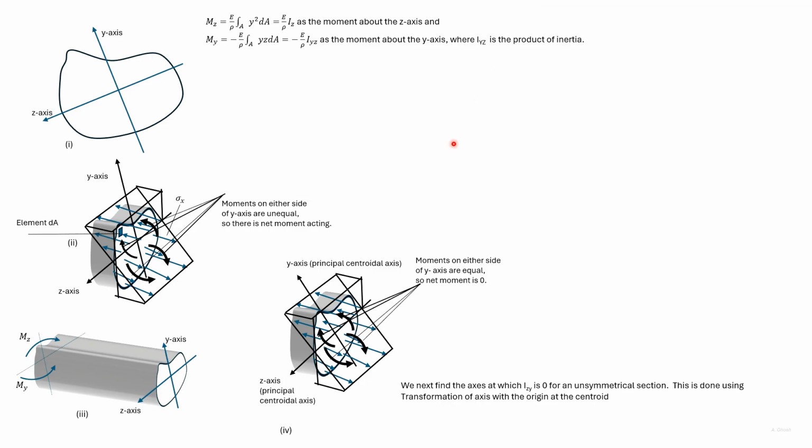As mentioned earlier, we considered symmetrical sections subjected to moment about both the axes as well as an axial force. So, with a symmetrical section, if there were moment acting about both axes, we would be able to find out the corresponding position of the neutral axis.